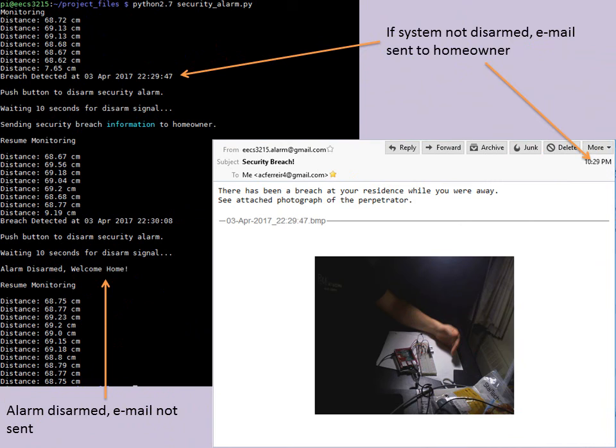In order to get our security system up and running, we need programming tools that produce software able to do several different operations. We need to manage the GPIO pins in such a way that the microcontroller correctly identifies input signals versus output signals. We also need to create routines that can monitor the state of the sensor, keep track of time, take photos and send emails with attachments, wait for button presses to trigger interrupts, and create threads that can blink an LED during an intrusion. We found that Python 2.7 handles all of these problems quite well with its varied libraries.